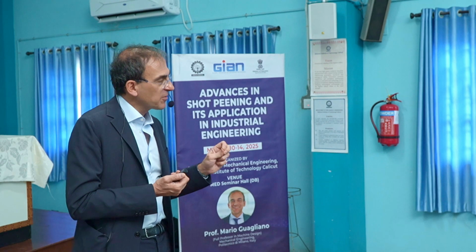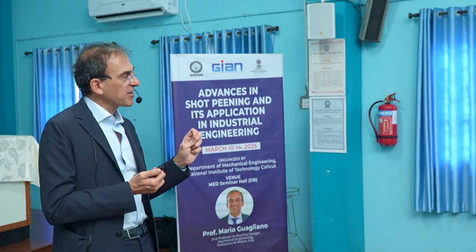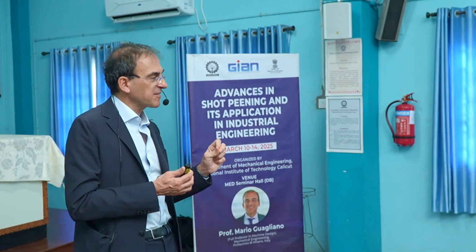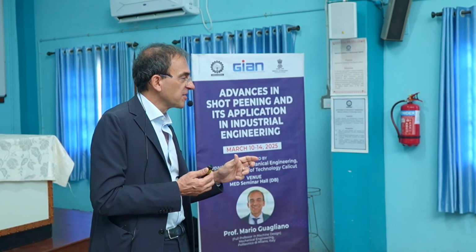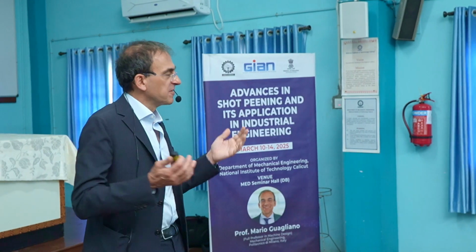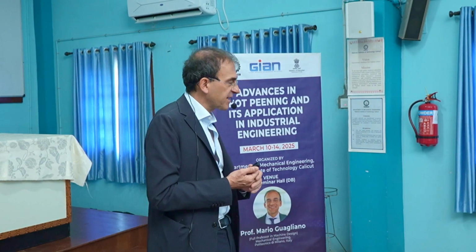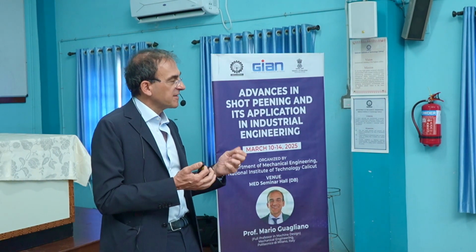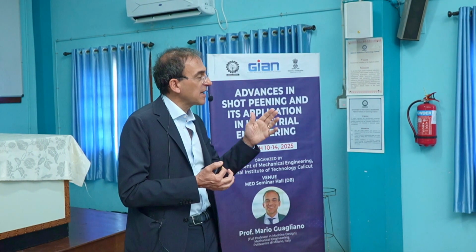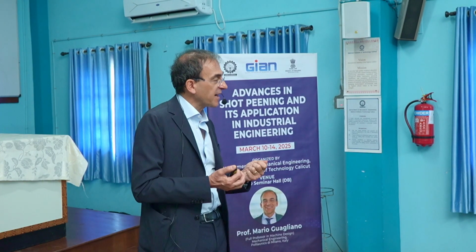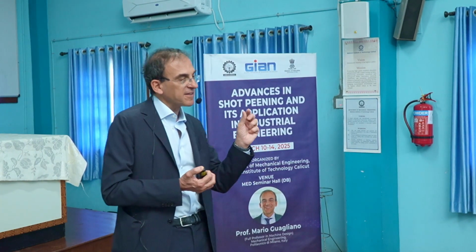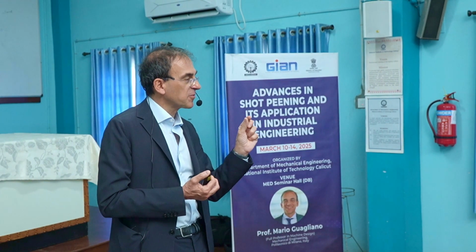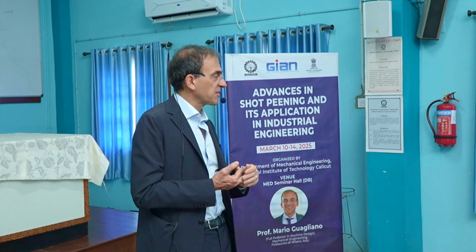For aluminum alloys, the usual way to apply shot peening is to try to induce the maximum stress close to the surface. This is for the practical application, for who is performing shot peening with this alloy, who say that this is due to the damage mechanism of aluminum, this is more effective. Anyway, I would say that it's better to try to induce a suitably deep residual stress field.